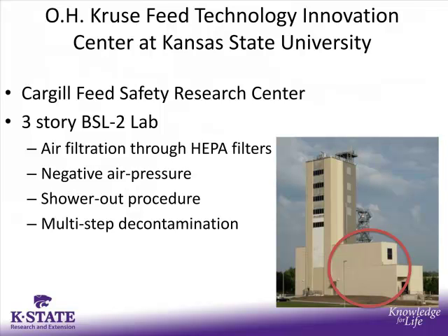All HEPA filtered air, negative air pressure, shower-out procedures, shower-in procedures if you choose that as well, with a multi-step decontamination, starting with a physical decontamination, going to a couple rounds of chemical, but then the final kill step is a process where we're able to heat the whole environment up to 140 degrees and maintain that temperature for 48 hours to really act to kill anything that might be left within the environment.